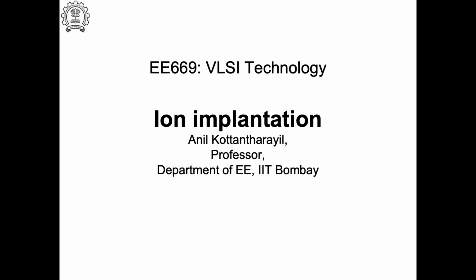Okay, so which means that when you do the ion implantation, you inevitably create damage in your crystal lattice. So this is not a good thing. Which means that the ion implantation has to always be followed with an annealing, a thermal treatment, to bring these things back and remove the defects. That is not bad, because after the ion implantation, I don't need the photoresist or mask. I remove the mask and do the thermal annealing. So this is a very important thing.